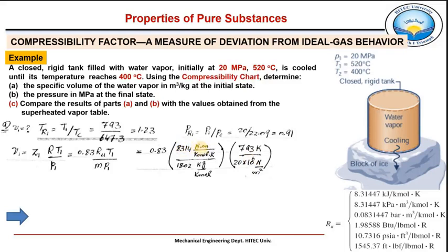Newton meter means joules, or kilojoules. If you transfer it to kilojoules, then it should be divided by 1000 and 8.314. But pressure is in pascals, so that's why it should be in joules per kilomole per Kelvin, divided by 18 kilograms per kilomole. Temperature is 793 Kelvin.